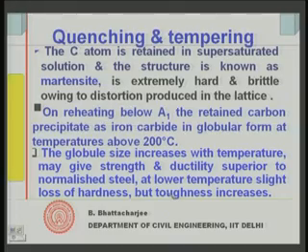So, first I do quenching, cool it rapidly, and if I reheat it, it would behave like this. Well, a similar sort of effect I can get. First I quench it, but then do not reheat it, but allow it to cool slowly, or temper it by retaining the heat, so that it remains tempered. First you cool it quickly, then you reheat it in a way, and cool it, and that is what you get. Okay. So, by the tempering process, that is what you get.